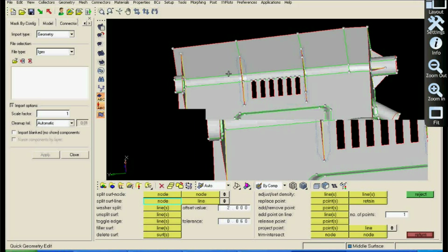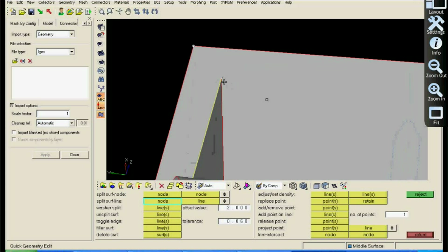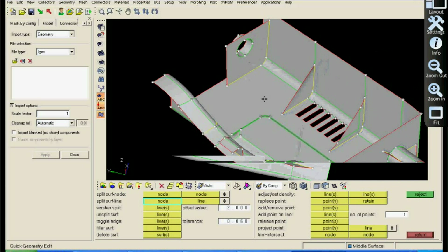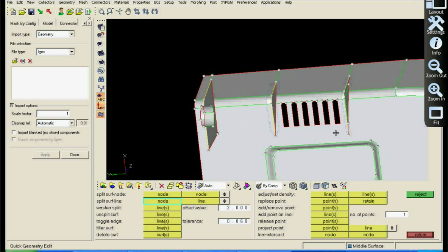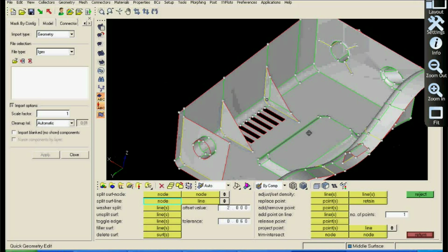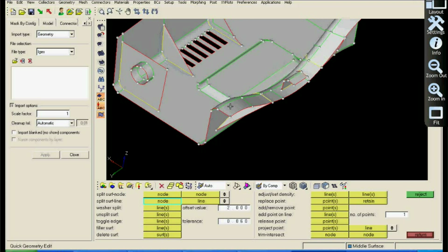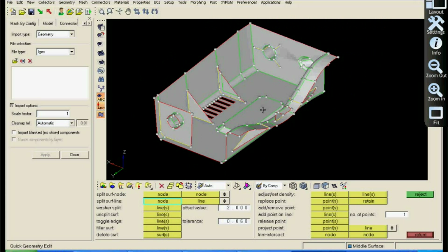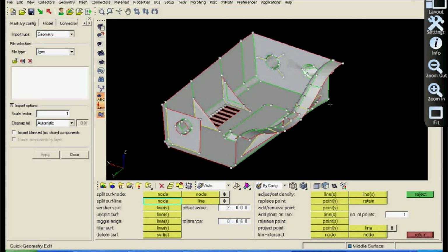One can also think of creating a cut here as well, so we can follow where it is breaking and where some parts are intersecting and so on. But again, this is totally different from one person to another. Somebody may not like to create this cut, and still go ahead with the mesh. That is totally different from skill to skill and person to person, and nobody can decide this is the only right way or that is the only right way. At the end, we must have a nice mesh, and it should pass the quality criteria. That is what our aim is. Whether you create such cuts or not is totally a matter of personal opinion.